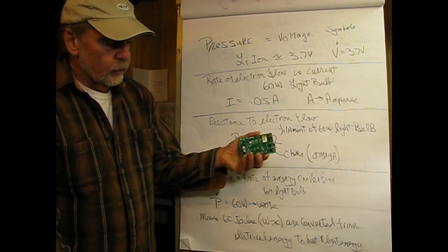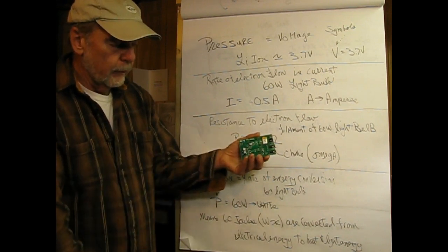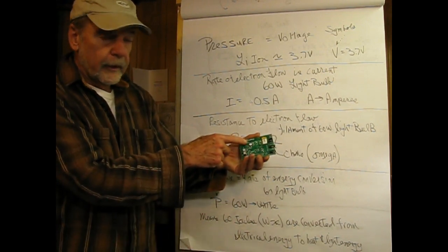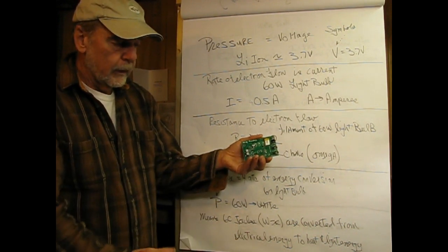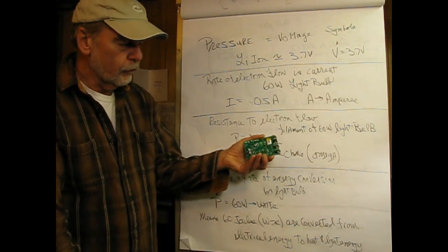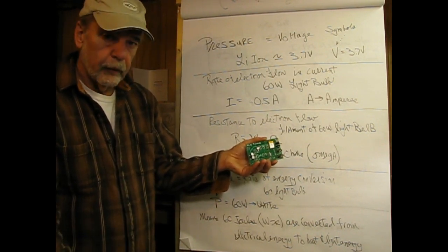Now when I flip that switch, what we have is a current flow out of the negative terminal of the battery through a light emitting diode, through a limiting resistor, and then back into the battery, in addition to powering up the rest of this circuit, which basically does some unique things with audio.